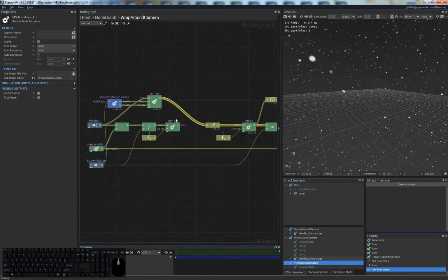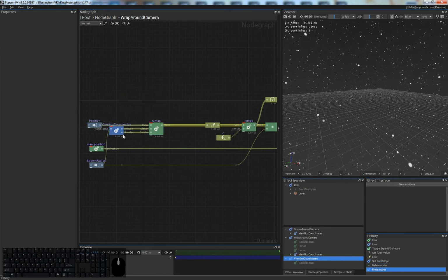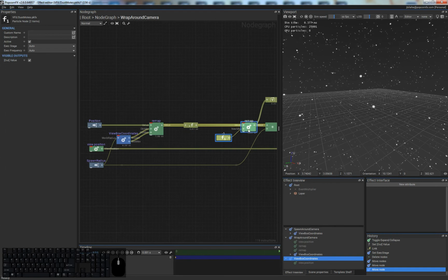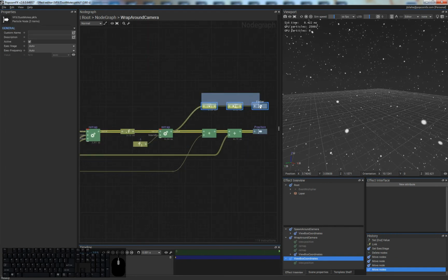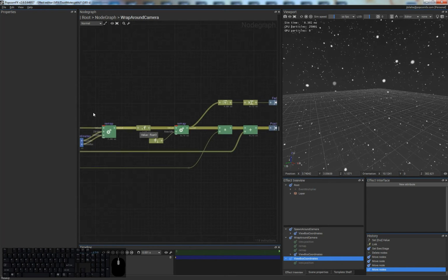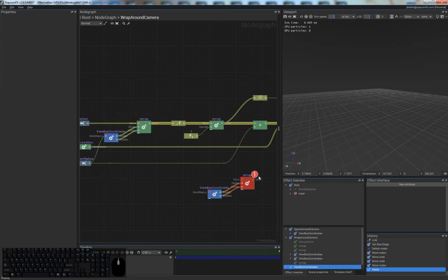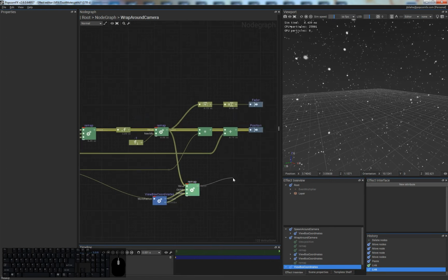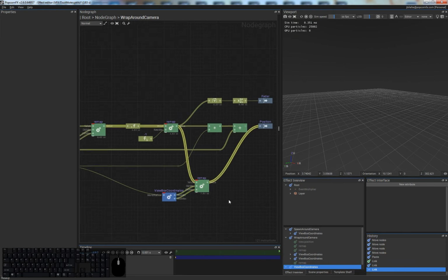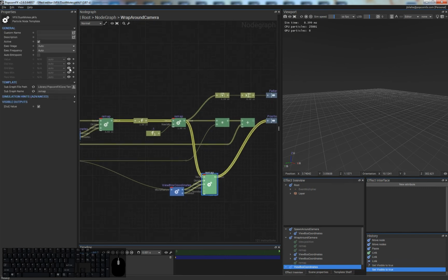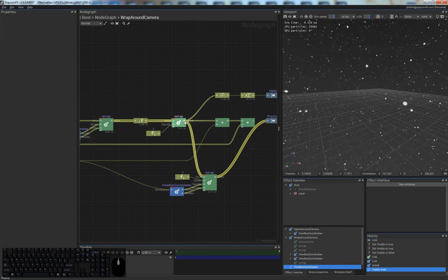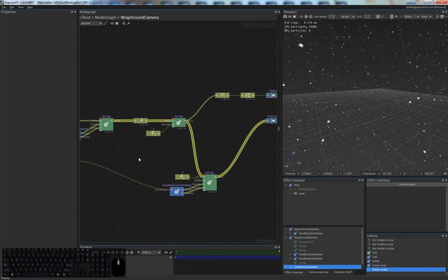So this still works. We can get rid of all that, and it is now a generic way to remap the box coordinates into the 0, 1 range. We need to keep that remap between 0, 1 to -1, 1 because we are using it for the fading distance, but likewise afterwards we can just reuse a remap node and take that and wire the result back. So if I wire it as is, it will disappear. That's because I'm still using the old min, old max here. I actually want to remap to the box coordinates as the new min and new max, and to say that the old min is -1, because here outside, when I'm taking the value out of this remap, I'm in the -1, 1 range. So I can also delete that.